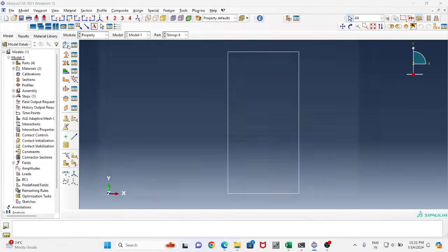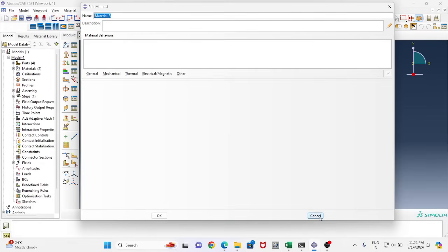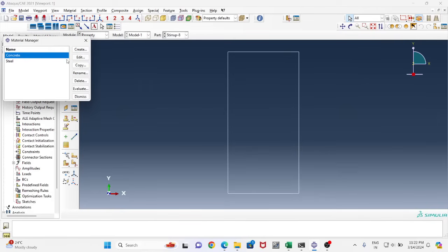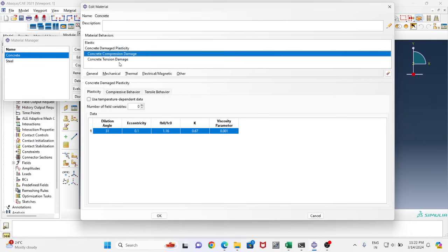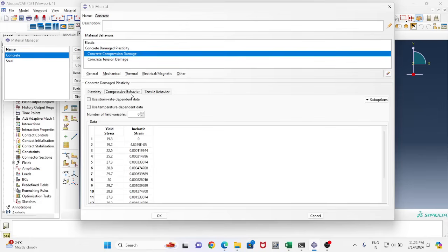And not to forget, while defining the concrete material, we just got data from a reference. You can also get it from experimental data, which will be more accurate. You can use references as I did, or you can use models to represent the stress-strain curve behavior of the concrete, like the Hognestad model, for example.